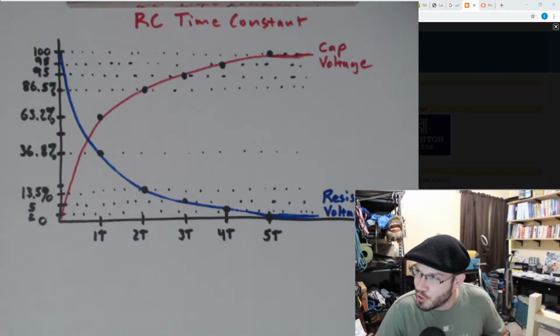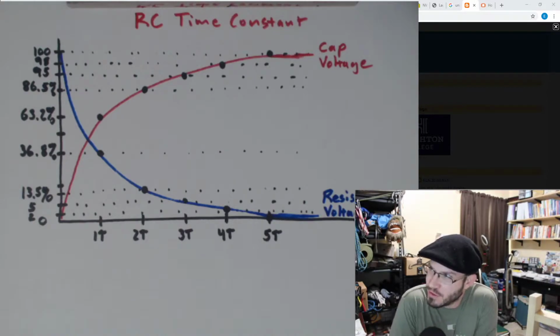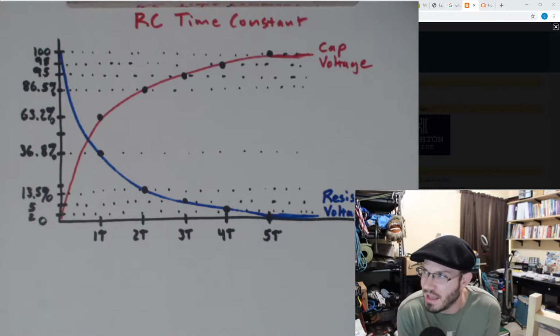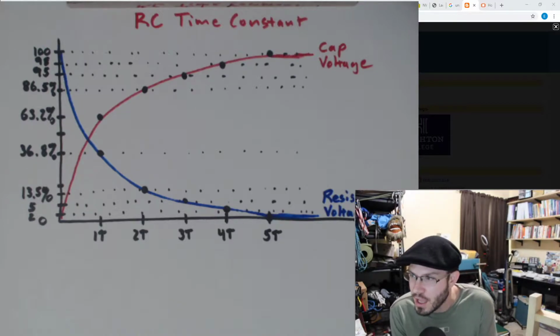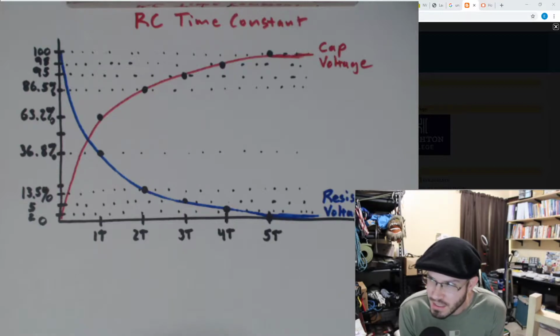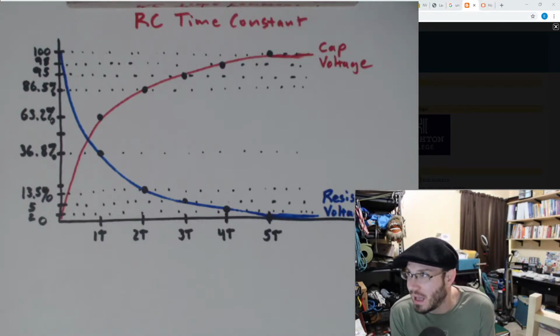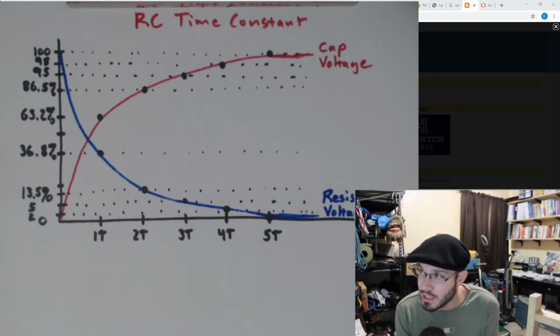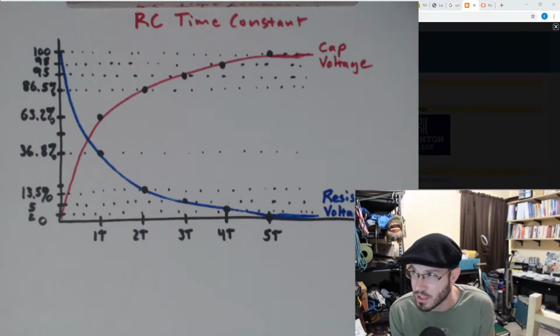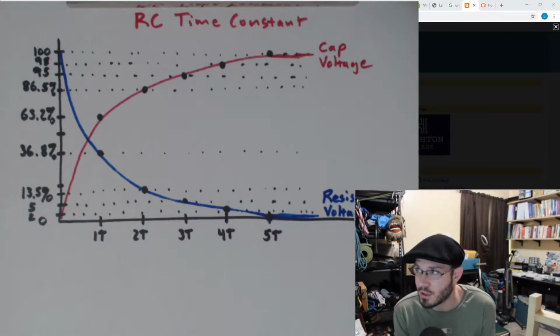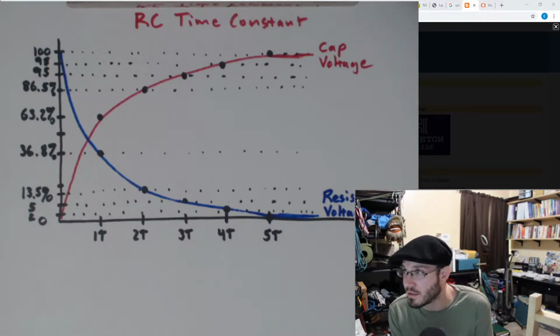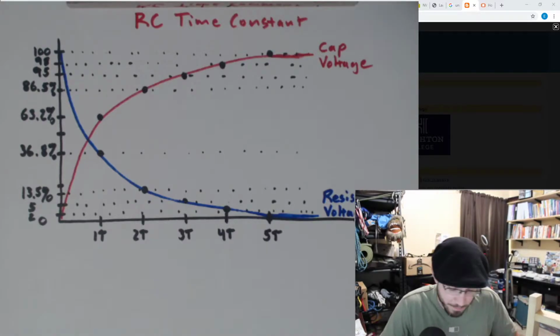So last time we introduced capacitors. Capacitors are a little circuit element that is capable of storing charge. When we store charge on the cap, it develops a voltage across it. Similarly, as well as charging the capacitor, we can discharge it. As we pull charge off of the capacitor to power something else in our circuit, the voltage would decrease across the cap over time.